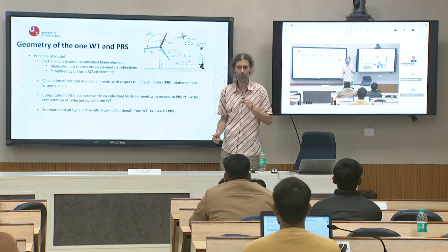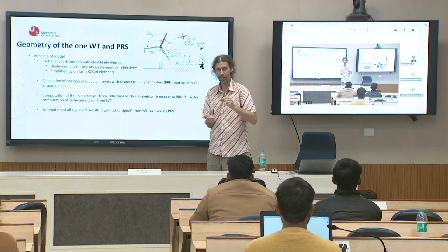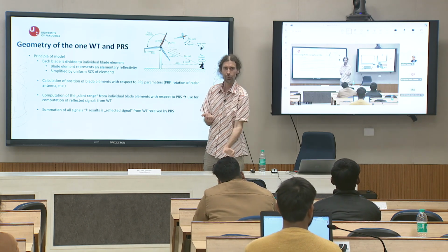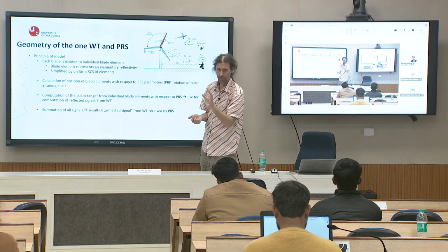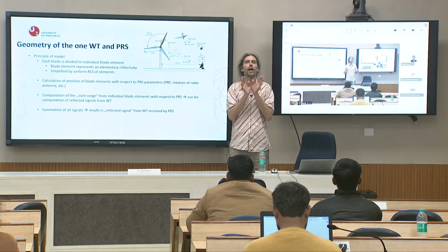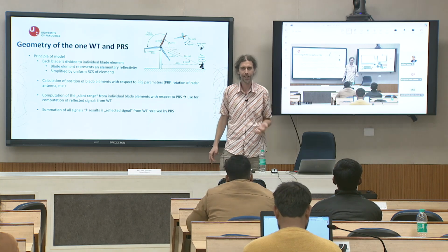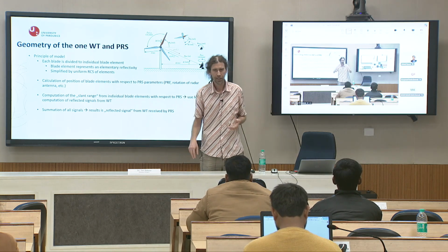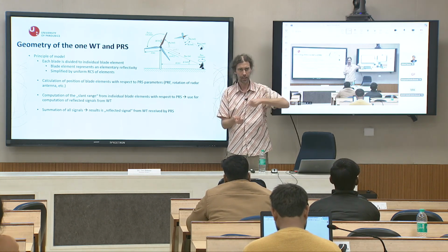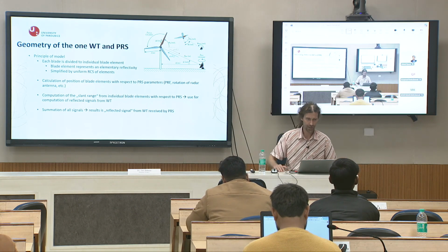So I also need to count how long this pulse needs to get to this blade element and reflect back, and to each element of each of the 3 blades, to each tower, and everything is variable in time. If it were a continuous way, okay, I am watching and just gathering the reflection signal, and it is relatively not easy, but easier than our case. But we work in pulse regime, so I am sending a pulse and getting an answer. So it is a much worse case.